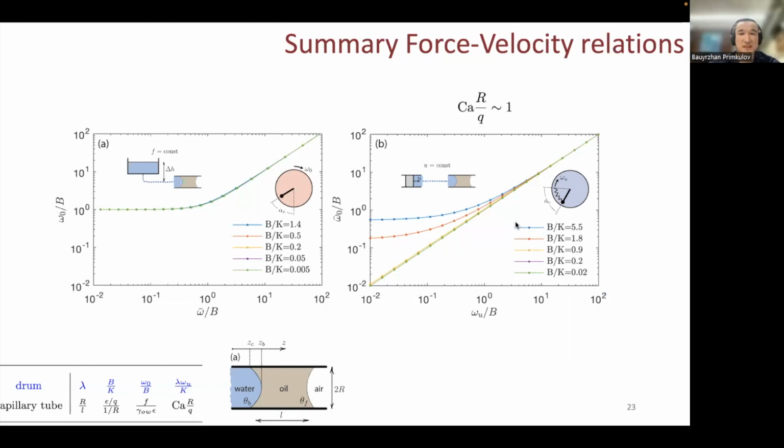Okay. Now, just to recap what we did here, we had a simple experiment that motivated the entire study, where initially we saw the slug with a misbehaving contact line at the back. So that's a liquid-liquid contact line. And we saw that you could nicely convert the equations of motion of this slug into a system of equations that describes a pendulum that's driven by the motion of the outer edge, so that's the constant force analog, or you could think of it as a constant rate analog. So that's when you're pulling the pendulum by the end of a spring.